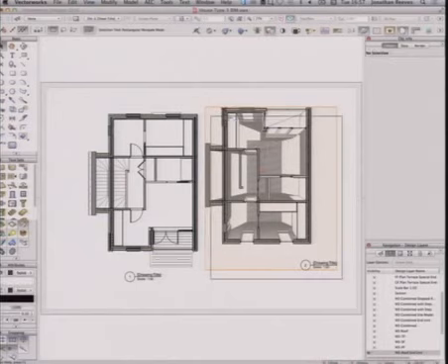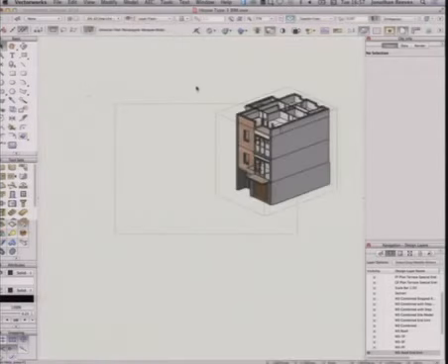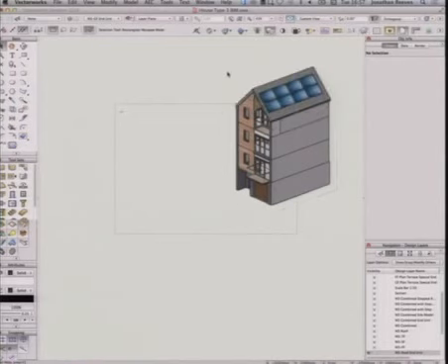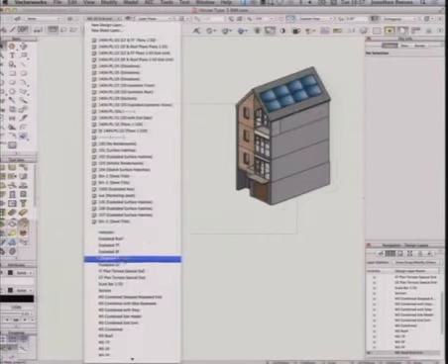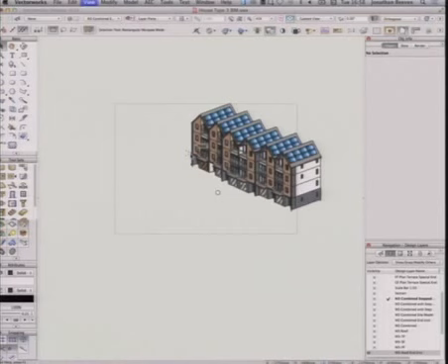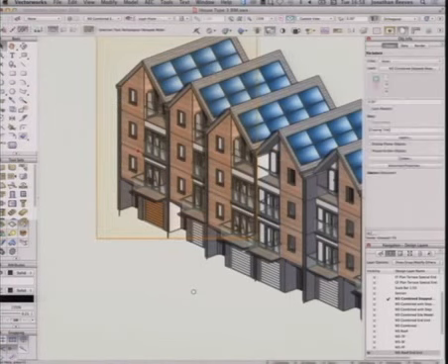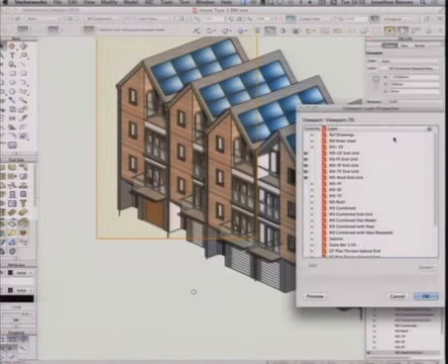Okay, good. So what we've done is we've created our little model here, just showing you how to create a couple of sections. Now what I've done, I've basically gone to another layer in Vectorworks, and I've used something very powerful called a design layer viewport. So each of these bits of building is an entire viewport, and that entire viewport assembles together various design layers. So it's like a lump of information. Think of it almost like a giant symbol for the whole building, but it's not, it's a viewport.